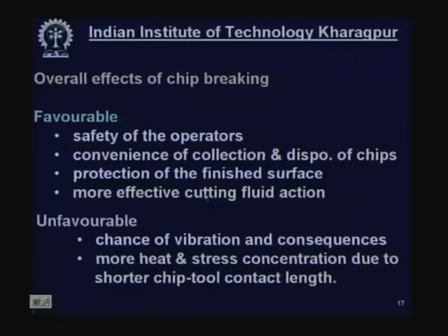Now, as I told you, because of this pushing of the chip upward by the heel, the contact length between the chip and the tool decreases, and through the small contact length the cutting fluid comes closer to the cutting edge or the chip-tool interface, and then the cooling and lubricating effect becomes more effective.